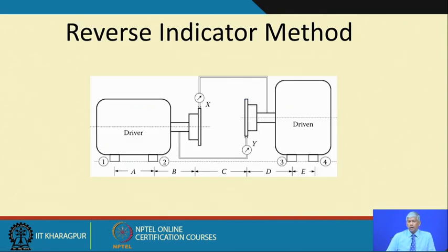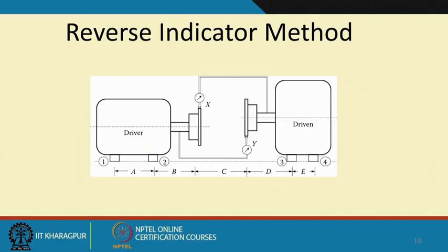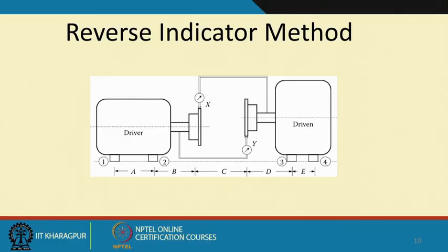But the question is, I very crudely told you that we can measure by measuring the vibrations at 12 o'clock position, 3 o'clock position, 6 o'clock and 9 o'clock. Okay, and by measuring the vibrations, we can see whether there is a strong axial component. I would be confirming that it is the case of misalignment.